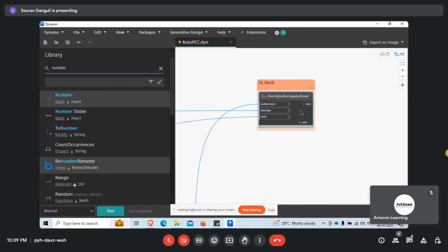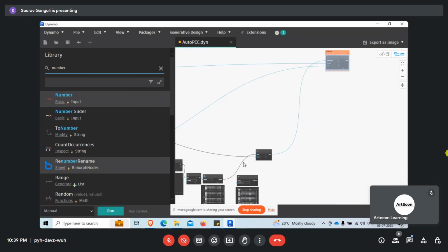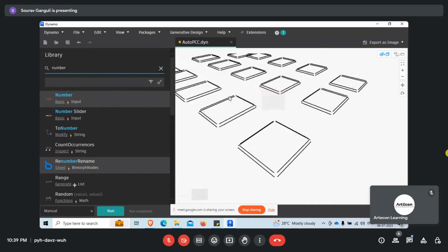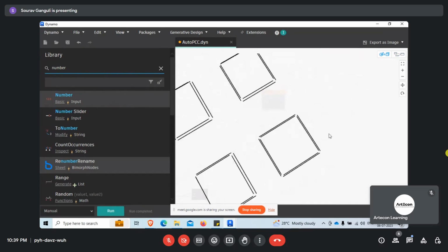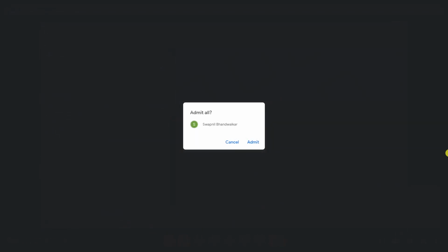let me freeze this node. We do not want the floor to be generated. So this is how it would have gotten offset. And see, there is no order to this, and we would not have been able to work with these points after offsetting. If we offset the curves individually, there would have been gaps and everything. So in order to avoid that, we use PolyCurve.ByJoinedCurves to get clean curves, which we then could offset a specified distance.